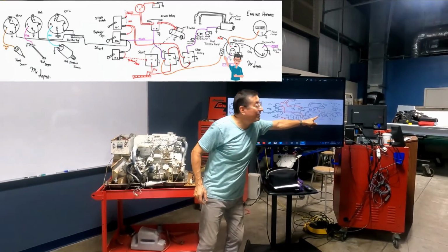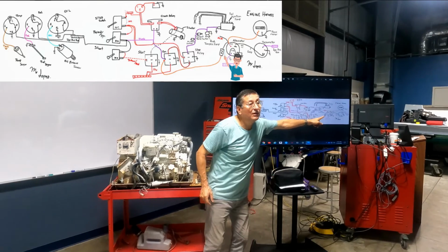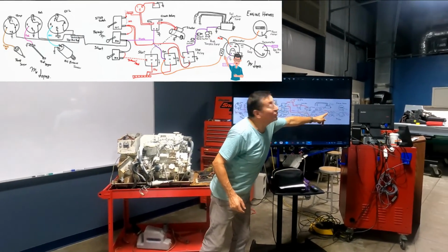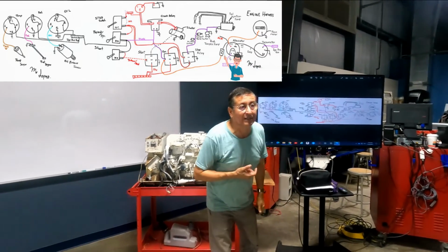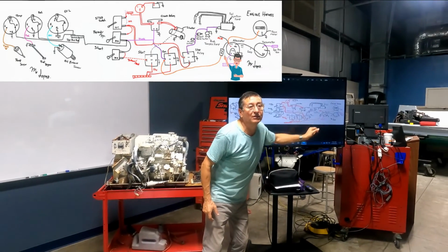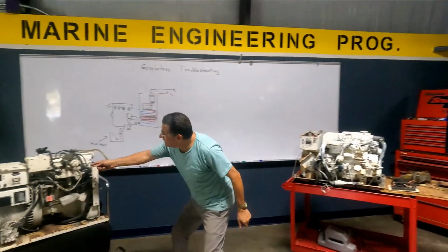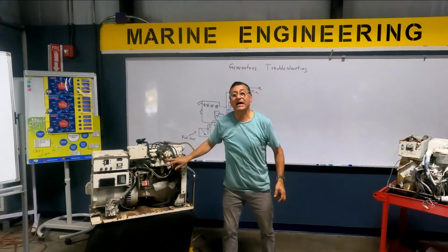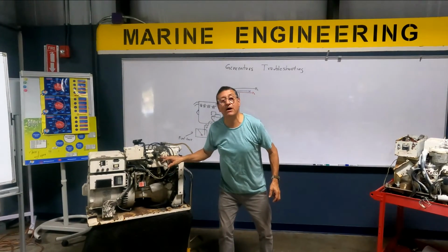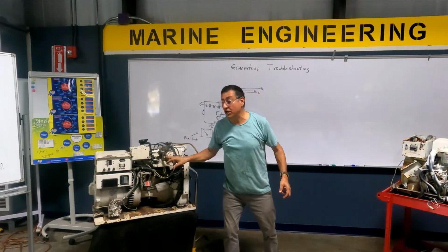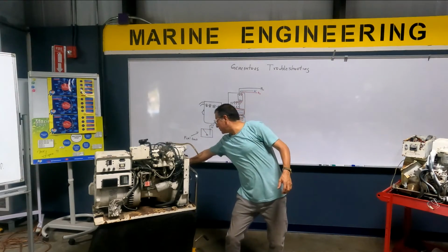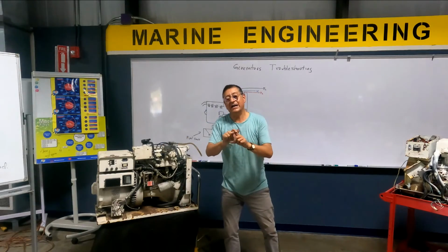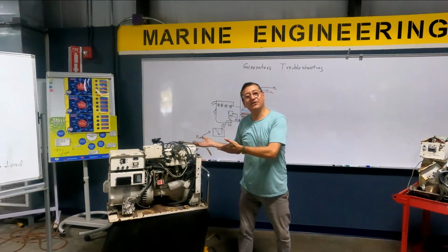And you remember that in the output of the alternator you have one diode over there. What is the function of that diode? When you preheat, it's not a good idea to introduce current here in the output of the alternator. For that reason you have that diode. This is the diode here. Look at the diode. The diode controls that you have constant power here. When the engine is running, the alternator of the gasoline engine sends power, and the solenoid stays open and the generator continues running.